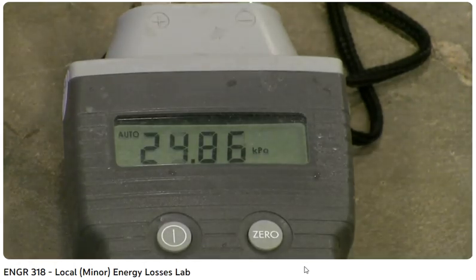Let's go ahead and gather the data, but then put maybe an asterisk next to the 90-degree T, since I wasn't able to get flow through that upper tap. And we are measuring a pressure differential, but it might be that whatever hole there is between the tube and the pipe is very small, and so there was a low flow rate, but I can still measure a pressure differential. Anyways, let's get some of this data.